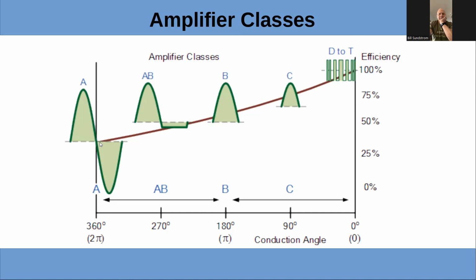Okay. So versus a class D, just so I pick up where you're going, class D is a modulating system. So the modulation is what reduces the inefficiency or power consumption, right? Because your active devices, your transistors, let's say, are either off, at cutoff, or they're at saturation. So there's very little power dissipation in the device. It's either off or on, not in the middle, which is where a class A is.